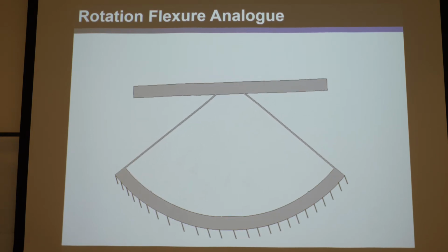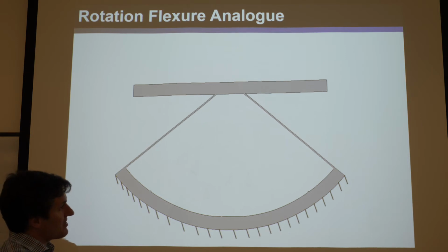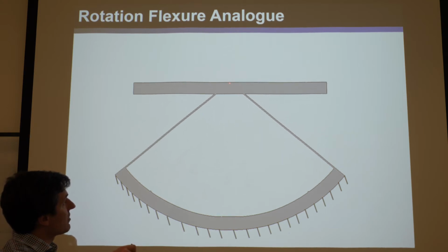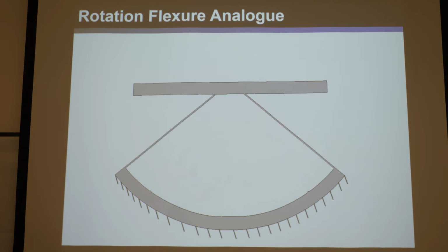And by the way, this is just one of possible under-constraint eliminators. But say you have a rotational joint, a revolute joint that rotates at the instant center of these things. Again, it's got whatever size it is. It's symmetric. But the problem is that it can't rotate terribly far without yielding. And the axis of this rotation, which is right here where you see the red dot, over large deformations will actually drift over to the right as it deforms larger and larger amounts, so it'll have a parasitic error.